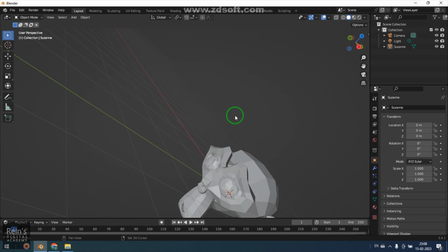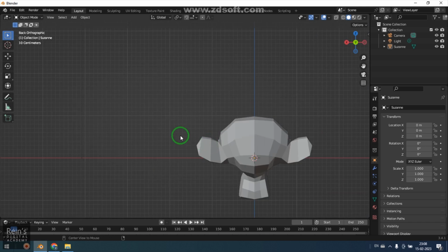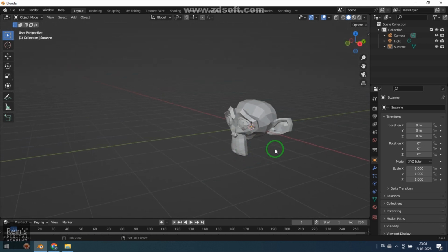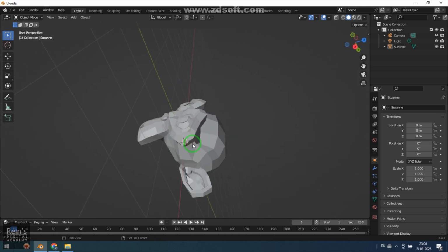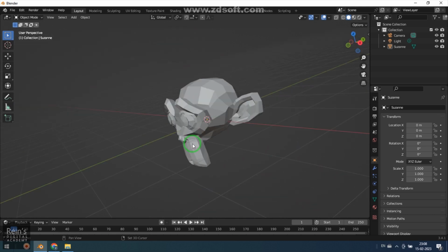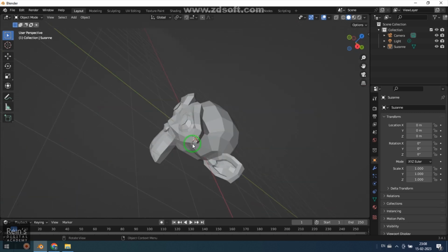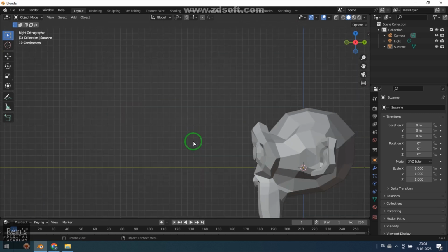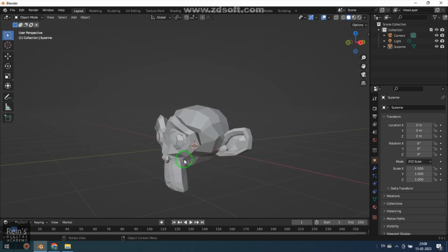When you are rolling the camera and you're in an odd view and you want to reset the view, just press 3 on the keyboard. I'll do it once again. I press Shift 6, I'm rolling it. Shift 4, I'm rolling it in the opposite direction. When I'm in the odd view, I can press 3, and it will reset back to the view here. So that's how I do the roll.